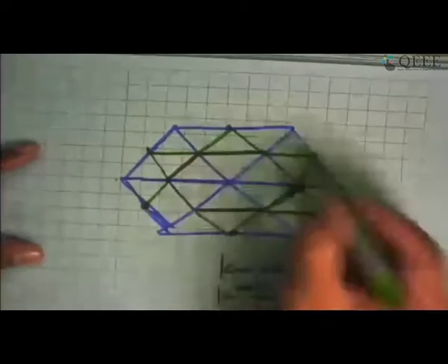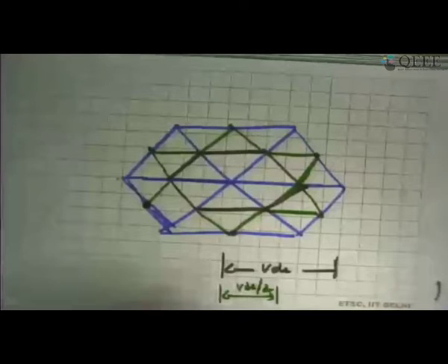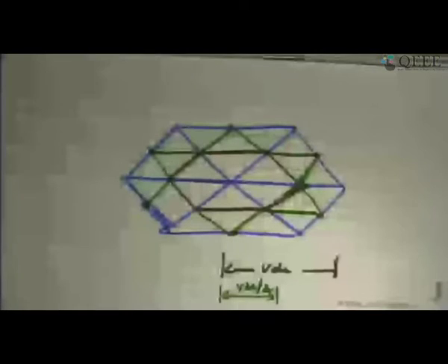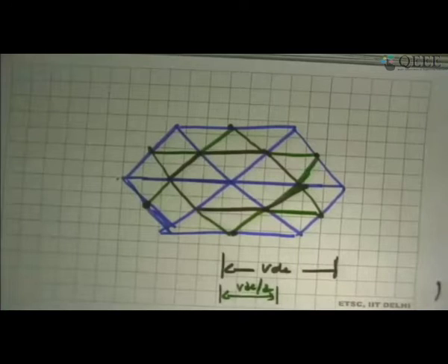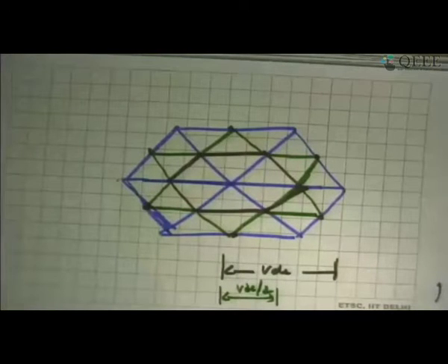Now we have a lot of active vectors spread all around the hexagon. So when you do space vector, you have a lot of possibilities of applying active vectors, and therefore the voltage stress is less and you get the number of levels more in the output.